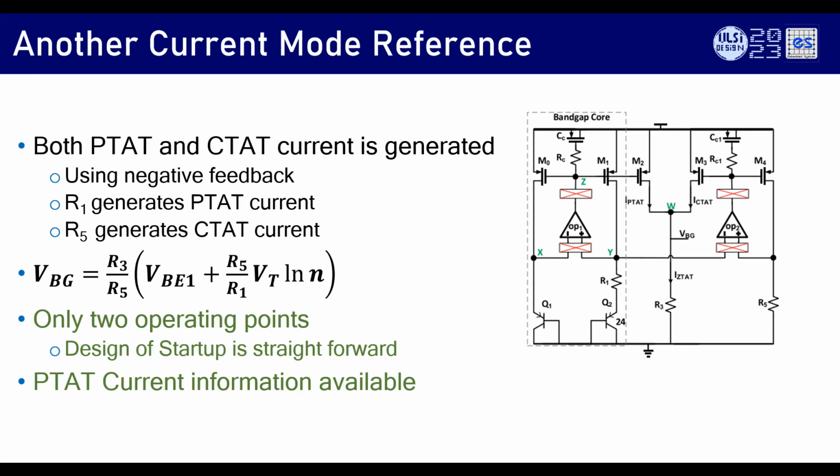Talking of startup, I just want to mention that at the time of startup, the operational amplifier itself puts a bandgap in positive feedback. You can think about it. I'm not going to explain, but it's a very interesting question. When the current is zero, if you look at the polarity of the operational amplifier, it becomes a positive feedback. That makes the circuit not come out at all. That's again a pain.